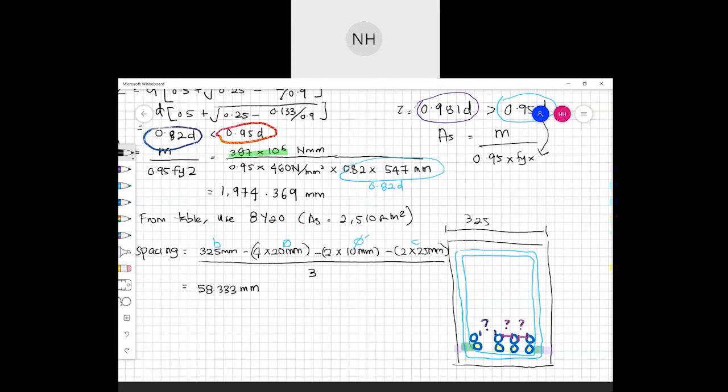So 58.333 ni kita kena compare pula dengan apa? So kita kena compare with something. So compare it dengan HAGG ataupun aggregate size plus 5 mm. So kita tengok dia lagi besar daripada aggregate plus dengan 5 mm. Okay, because we know that aggregate size I cakap sebelum ni 20 mm. So 20 plus 5 mm, 25. So 58.333 is bigger than 25 mm. So maksudnya okay lah. Okay.